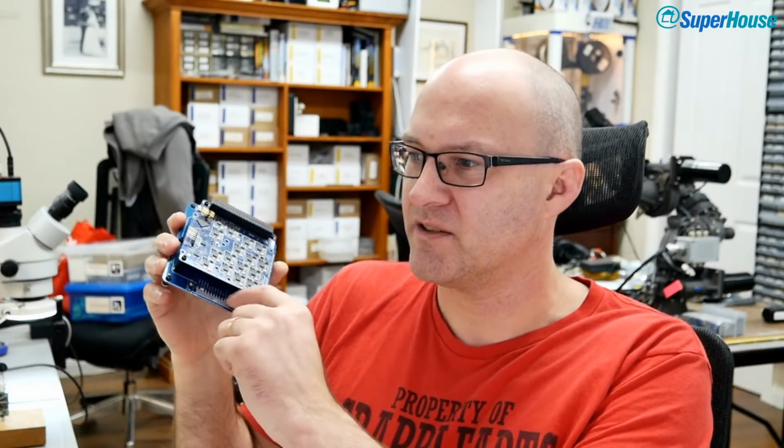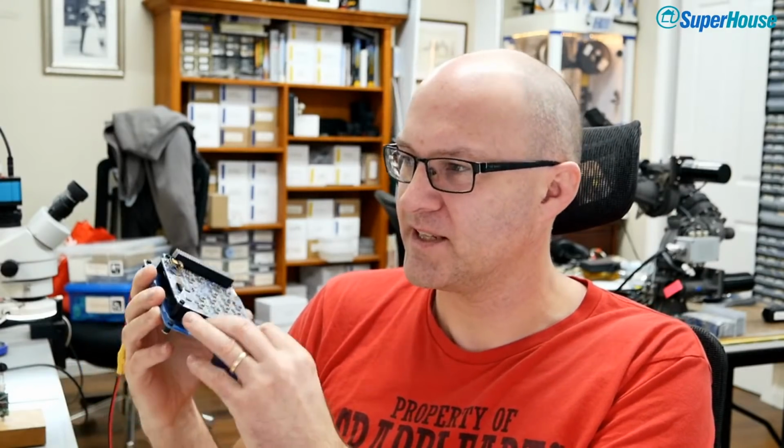So there's a connector on here which is a DB25 connector, and they are available in space rated versions, and you can also get a cable gland. So what happens is that there is a wiring loom that goes through the wall of the vacuum chamber, and it plugs into the device that's inside the chamber.